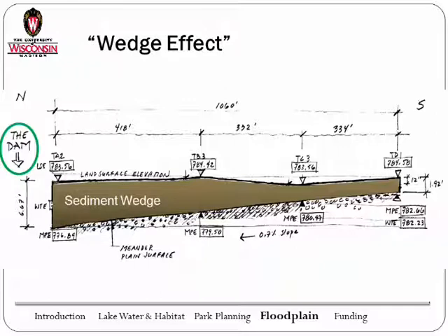We measured the elevation of that, and then we were also looking for some evidence of the land surface that was there before the dam, which we call the pre-settlement surface. The way we identified that was by a change in soil characteristics. Below that, we hit a series of gravels like this, and this would have been the old bed of the river from when it would flow along the floodplain there.